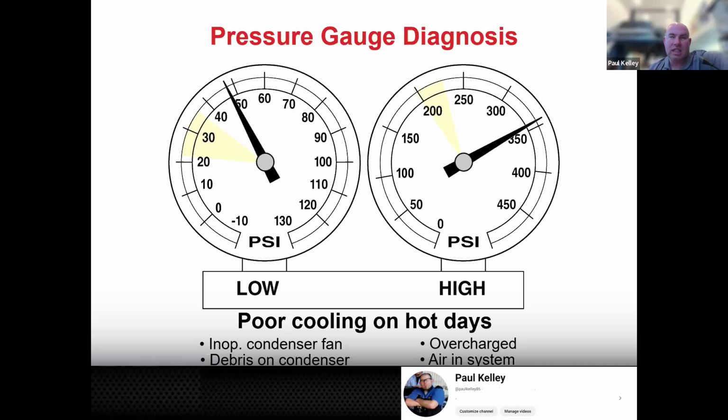So let's say that this vehicle were to have these types of numbers, but it were to have oily dye all over the compressor near that relief valve, I would diagnose that as probably air, right? Because the air came out and now it's normal. Cool. So that leak wasn't a leak. It was on purpose. It's a blow off valve, right?